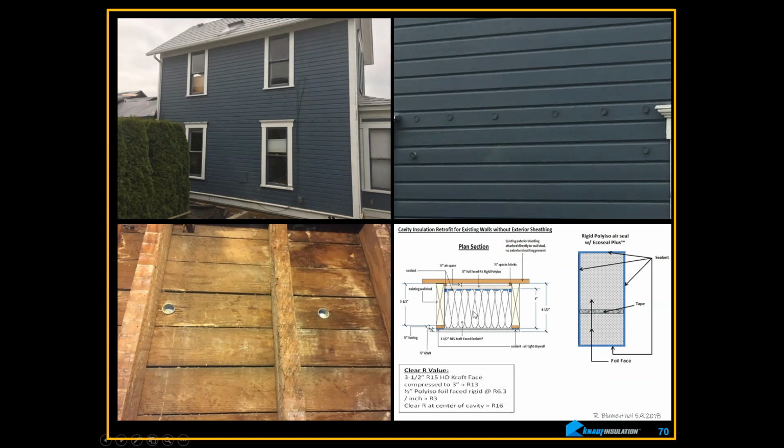So what we had to do in order to get as close as we could to an R20 wall, again, this is a remodel, without furring out the walls, taking off all the window trim and all of that, what I did was I designed something. So this is not the sheathing. This is actually the clapboards right here. So there's no sheathing on this wall. So there's no air barrier, not to mention the vents, but everywhere between the shiplap you get air infiltration in here and water.